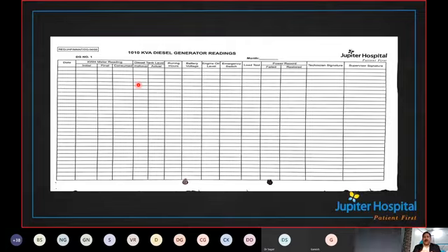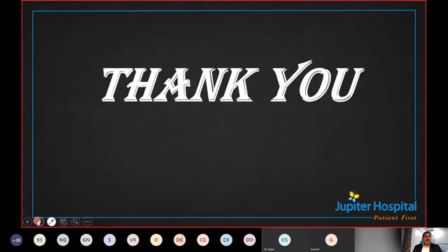We are having VFDs everywhere. For humidity maintenance, we have heat pumps. And importantly, the glass structure, the way we have put it, the U value is such that the patient will also get the daylight, as well as we will have a lower U value, because the lower the U value, the lower the energy consumption.